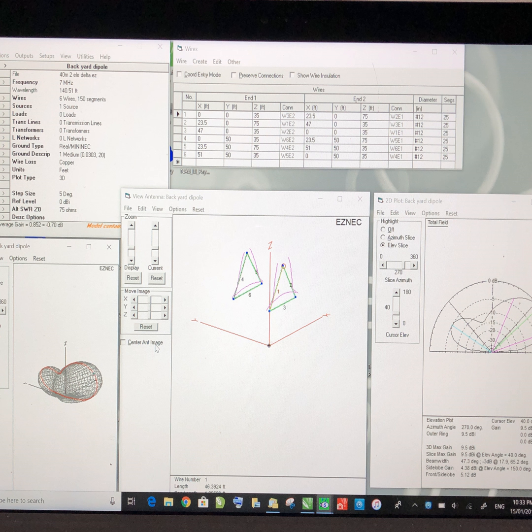And I've designed and built dipoles, verticals, quads, multi-element beams. And in each case, this is fairly good for sorting out what's really important. And sometimes the results are quite surprising in terms of the design of the antenna, the height above ground, the effect of bending the elements, or installing an antenna as an inverted V. And also, as you go lower in frequency, you find that when you're designing dipoles or loops, when they're low to the ground, it's quite hard to get that lower angle of radiation, particularly if the antenna is horizontally polarized.